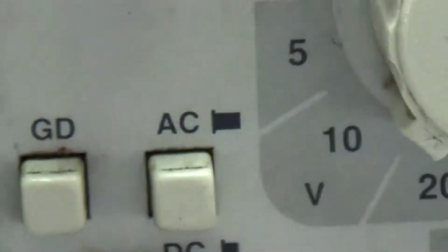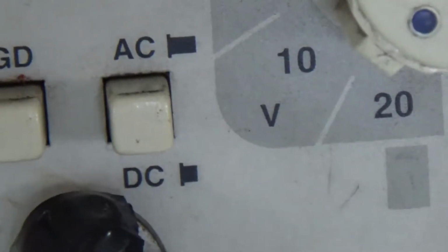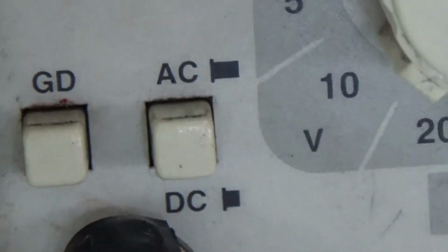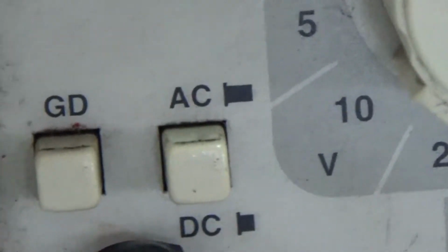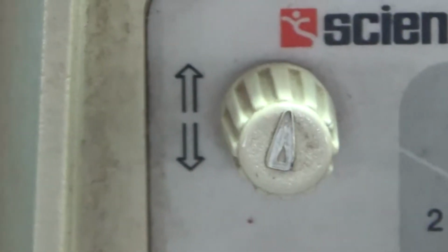Let me always set 5 milliseconds to ensure that every unit corresponds to 90 degrees. Now we set the end point of the pulses at 180. When you vary the DC voltage, we can expect the firing pulses to vary here. So this is alpha 0, alpha 90, alpha towards 180. Practically we cannot achieve 180, and even alpha 0 we cannot achieve. It starts from around 8 or 10 degrees and goes up to 170 degrees. So these are the high frequency pulses we expect at G1 K1.